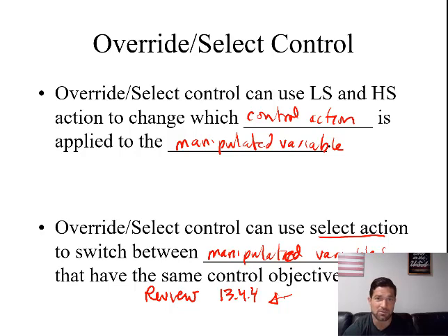In that case, what you would need to do is change from using the steam flow rate as the manipulated variable to the flow into the column as the manipulated variable. In other words, when the flow rate of steam saturates, you'll have to decrease the flow rate going to the column in order to keep your process at its specified value. We'll do that example next time and discuss how that works. But I want you to think about that beforehand. This is a really important example.